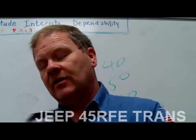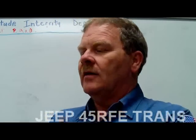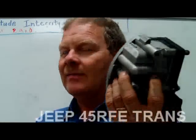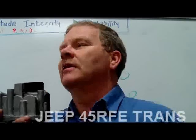But anyway, that's what you can look at. That is not hard to change. You've got to make sure you've got the right gasket with it. It'll come with it. A parts house has got one of these for like $150. And a lot of the times you'll draw a code. They'll throw you a code and it'll tell you you've got shift solenoid issues.